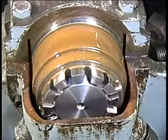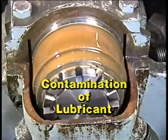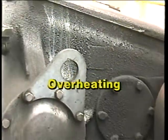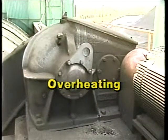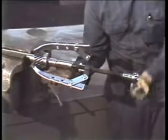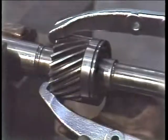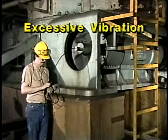Bearings often fail due to lubrication problems such as contamination of the lubricant. We'll take a more detailed look at lubrication problems later in this program. Another common cause of bearing failure is gear unit overheating. This condition could be caused by a number of things. For example, overheating could be caused by a buildup of dirt on a gear unit that's cooled by radiating heat to the environment. A third reason for bearing failure could be that the unit was damaged when it was first installed or during subsequent maintenance. Another cause for failure could be that the unit experiences excessive vibration when it operates.